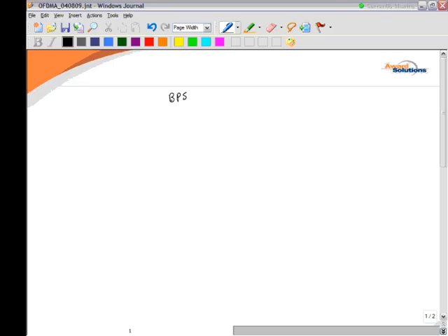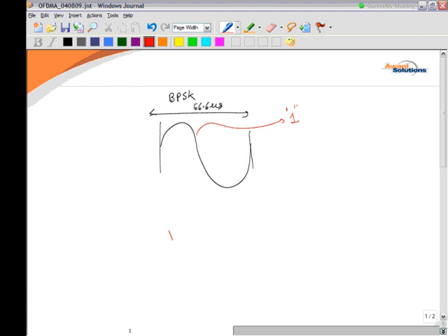In that case, if I have some modulation symbol period here, 66 microseconds, and I'm sending a BPSK modulation symbol, this would represent, let's say, bit 1. On the other hand, if I send a signal with another kind of structure, this is a sine wave here, this is a negative sine wave here. So I'm changing the structure of the transmitted signal. So this is another modulation symbol, so maybe it represents bit 0.